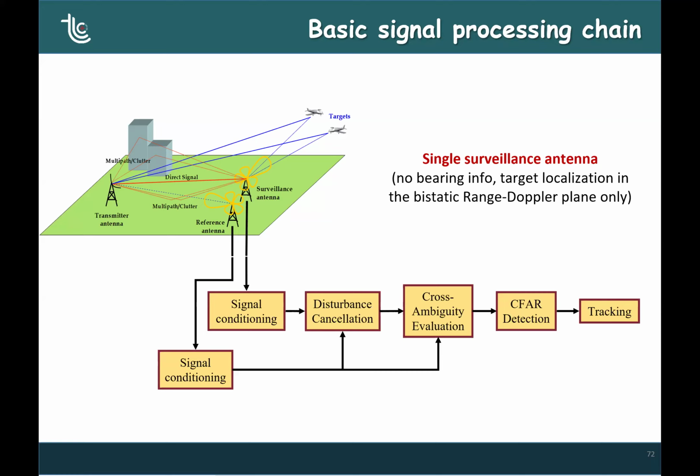But we have seen also that since the waveform is not designed for sensing purposes, sometimes it is not ideal for radar, and it can present high side lobes or peaks that must be cancelled before using the signal for sensing purposes.